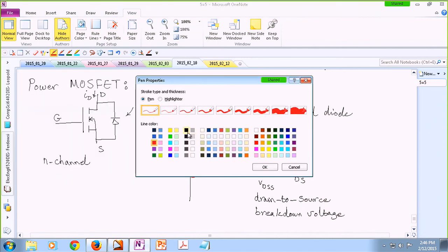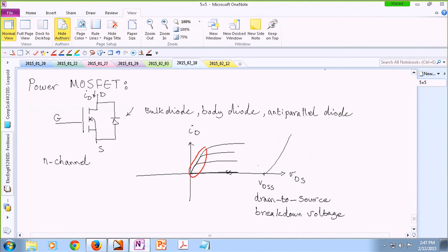Now, one thing to remember is that MOSFETs themselves are very, very symmetric devices. So in the negative territories, we almost have the same behavior, assuming this diode was not there, but the diode has its own characteristic, which is this, for instance. So in the negative territories, there is a competition basically going on between the device itself and the diode. If the gate signal has been triggered, the device is eligible to conduct negative currents.